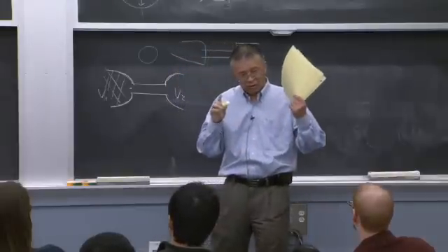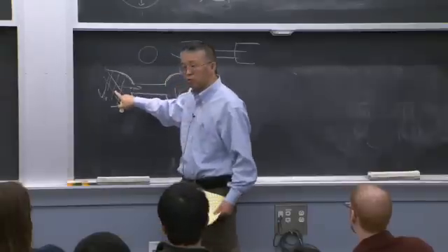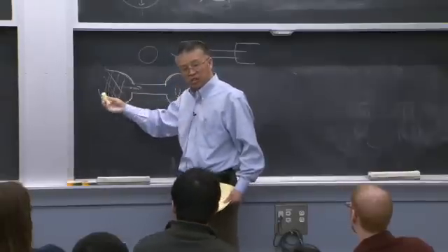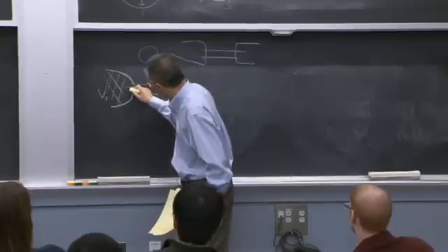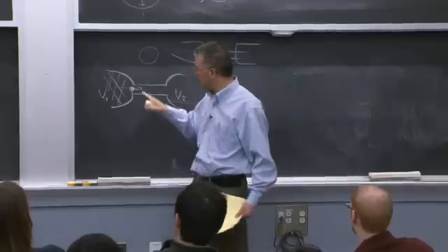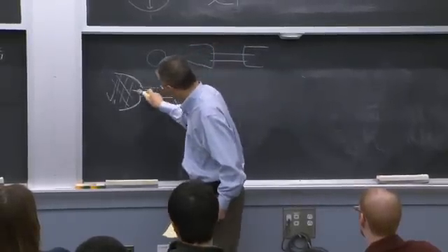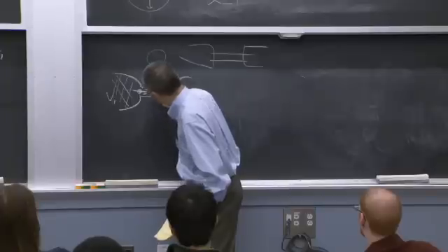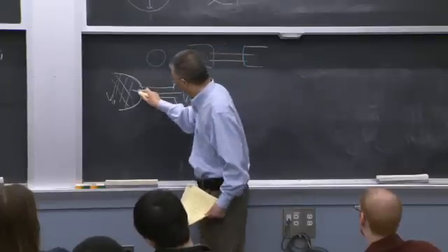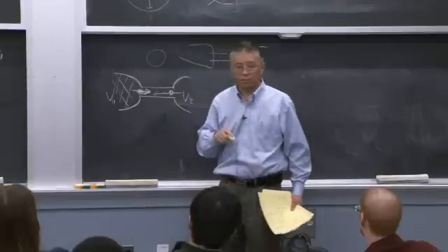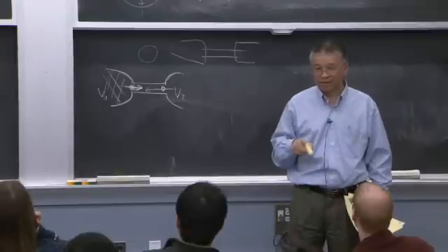So what that means is that what is launched into this region corresponds to what you measure. What's launched is your emitted electron. If you had a chance, there is a way to measure exactly the potential here of incoming plus ballistic going from this side to the other side, right? Then this point and this point are at the same potential. If you use that same potential, you get an infinite conductance.